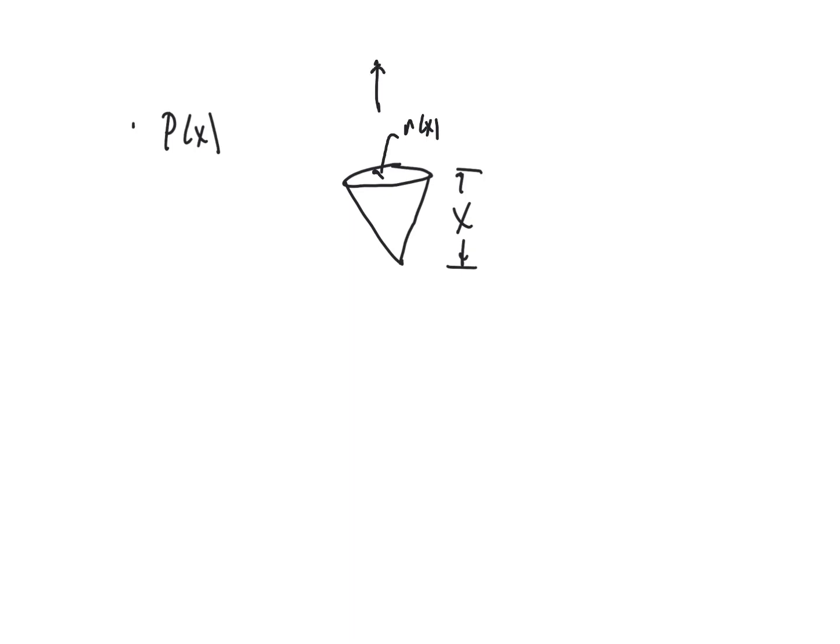And that's creating imbalance, so that the g is going down, so the weight is downward. That means that there has to be an internal force that's going to be in tension that's going upward. So that's the resisting load to the applied self-weight of that little partial cone.